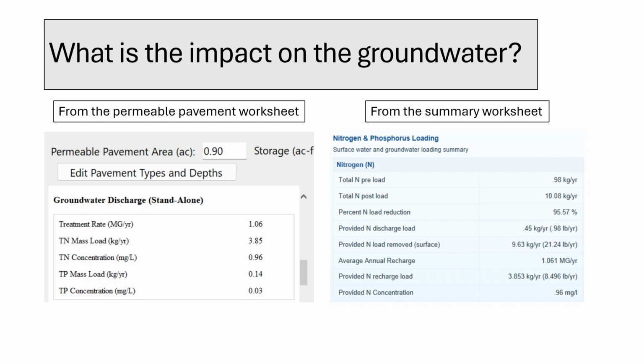It's crucial to understand the benefit provided here. If this water were allowed to infiltrate without the advanced sorption media, the total nitrogen concentration would have been considerably higher. Specifically for developed land conditions, it would have reached 2.24 milligrams per liter, and for agricultural conditions, it would have been 2.29 milligrams per liter. These higher figures represent the event mean concentrations, or EMC values, typical for those land uses without treatment.